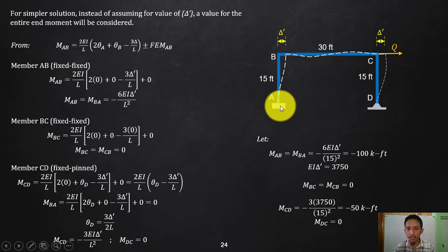If this will bend that way, for that to still be slope 0, the moment should counteract counterclockwise, or should resist that counterclockwise, so that of course it will not bend, just like a free support. That's why you ended up here actually with a negative. And with that, there is no force in between or in the member, so there will be nothing that will counteract that one, only the shear. Of course, if you try here, as you can see on the bending, that should resist counterclockwise, so still counterclockwise. So that's it for a fixed-fixed.